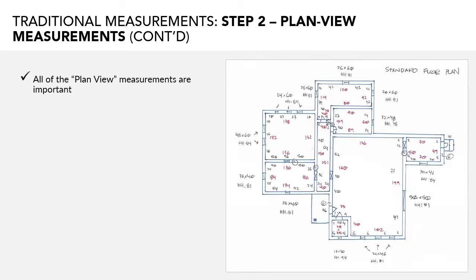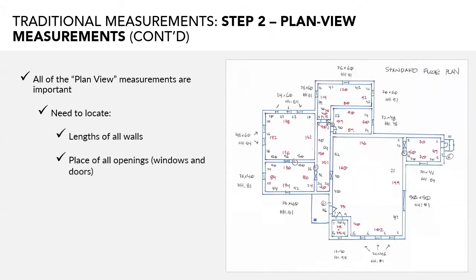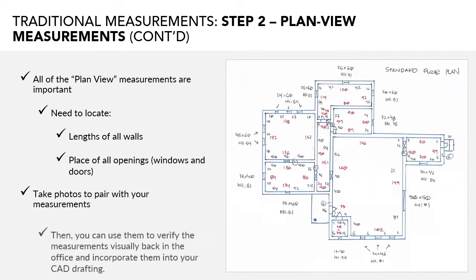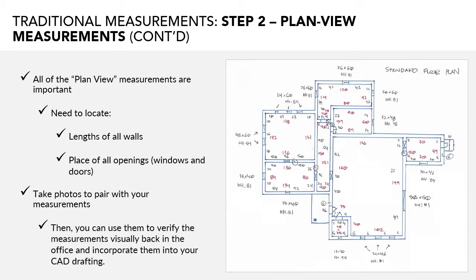In this sketch, you may notice that there are some overall measurements as well as some small incremental measurements. This is a good system of checks and balances that will not only improve overall accuracy, it may save you in the event that you have an incorrect measurement or notation. Don't forget to get good photo coverage. That's huge. That'll help you verify that what you actually are drafting is indeed correct. Occasionally, we've seen errors that don't appear right away, or on paper, but are obvious once you start getting into the images, and they reveal themselves very quickly.